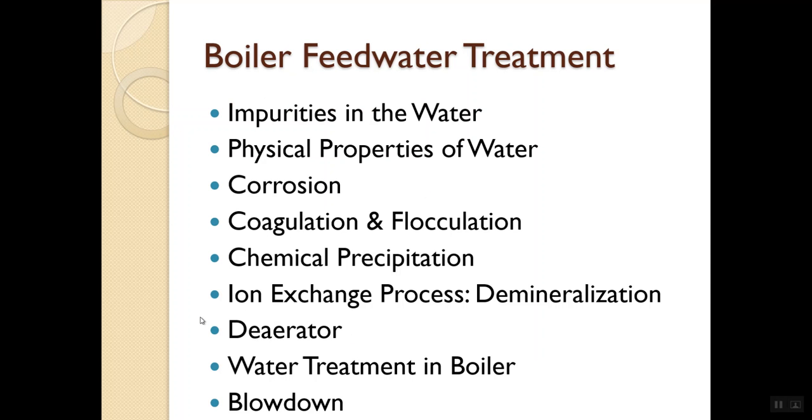Oxygen is bad to have inside of a boiler, inside of the water, and so we have to de-aerate the water. How we do that is we remove the air by heating it up. If we go back to the spaghetti, or the mac and cheese that we were making, if you've ever put a pot of water on the stove and turned the heat on, before it starts boiling, you notice little bubbles at the bottom of the pan.